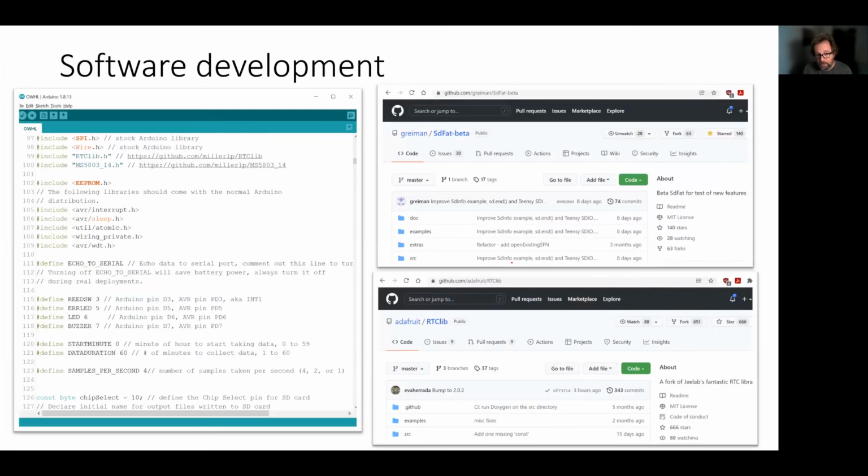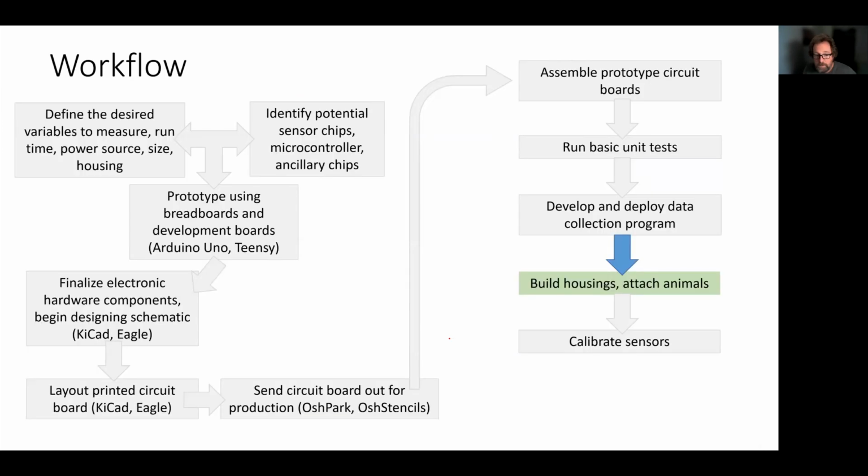And so the Arduino system is what I still use because it's nice free software. It's got a huge variety of freely available libraries that add on features. So for instance, you can download a library that allows you to talk to that SD card very simply. You can download a library that allows you to talk to your real-time clock, and you can paste all of these things together in a language that is effectively just C++ with bits of the original C language in it as well. So if you've programmed in something like R or Python, learning this is not a huge lift.